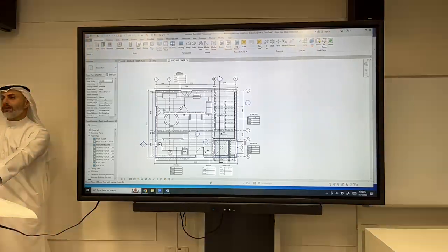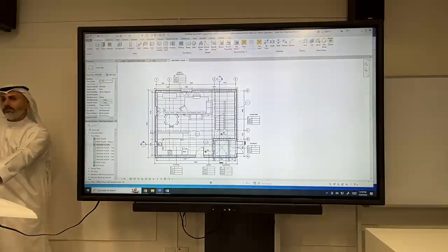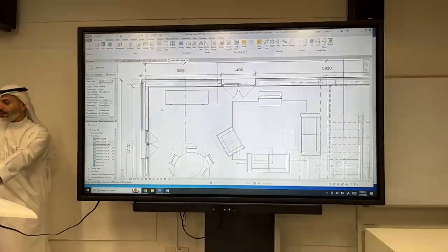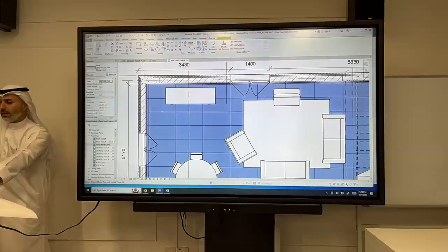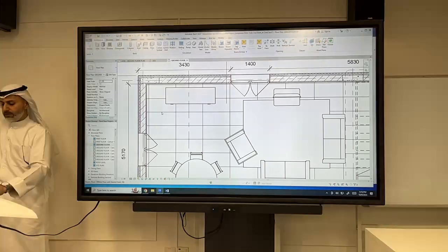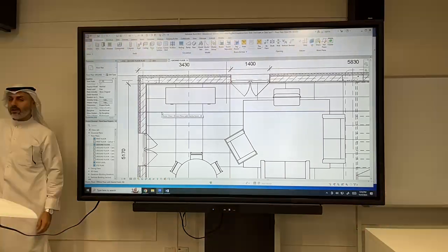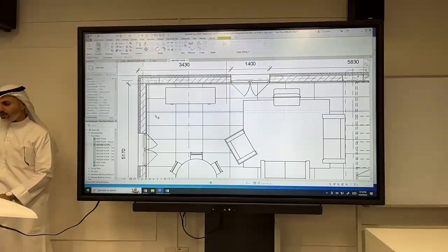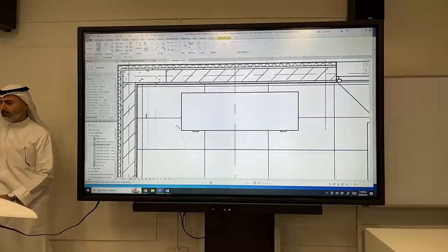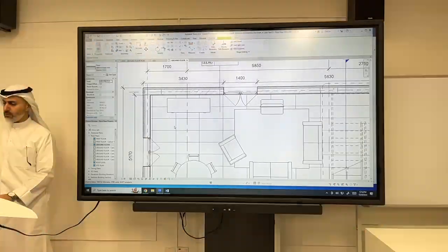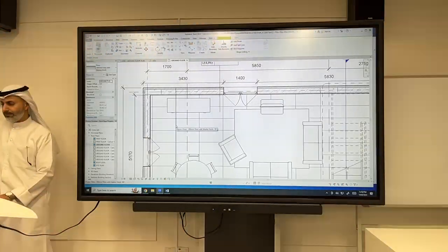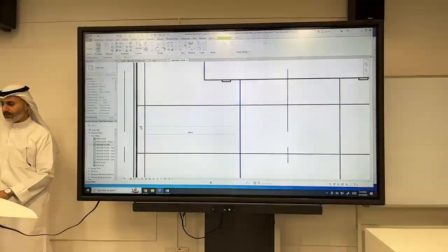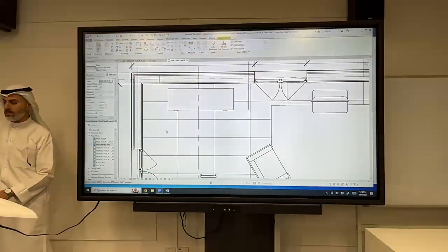Okay, do you remember how we can edit the floor pattern? Good, how do I click on the line? So you hover over the line, you hit tab, it highlights it in blue, and then you click once. We have two directions, so you're going to do it twice. Once in the vertical, and once in the horizontal. So go over one of the vertical lines, tab, MV for move. So try to use the shortcuts, it's faster. Align it with the walls.